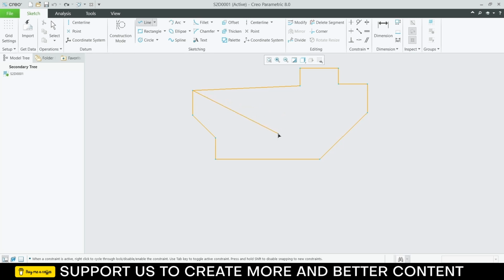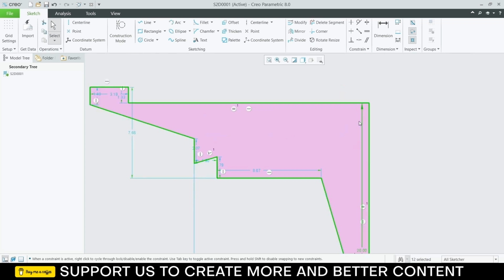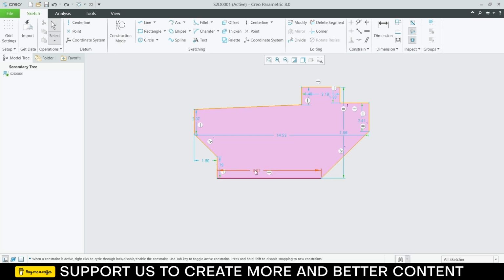Click on the middle mouse button to exit this command. Click on the middle mouse button again and get the dimensions of it. Now let's edit the dimensions. So this one is 20 mm. Press Ctrl Z. It is quite big. So let's make this one first big. So this one is 46 mm.